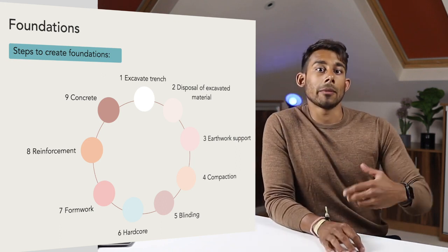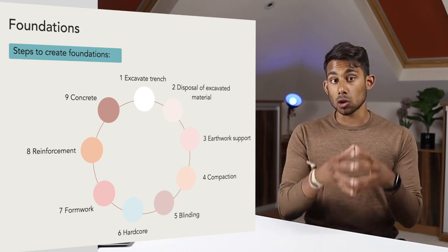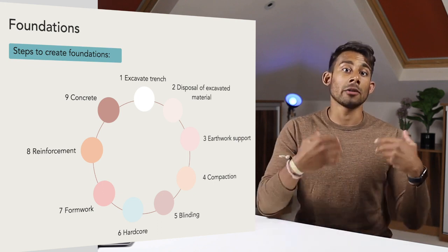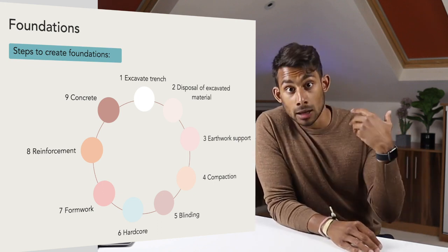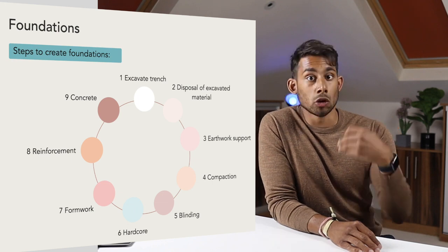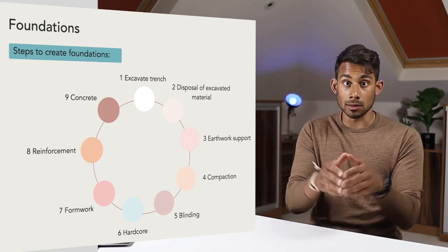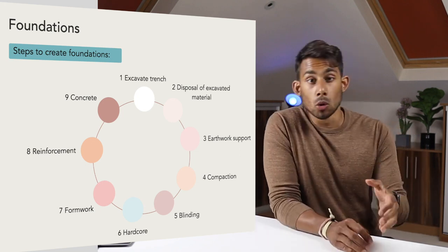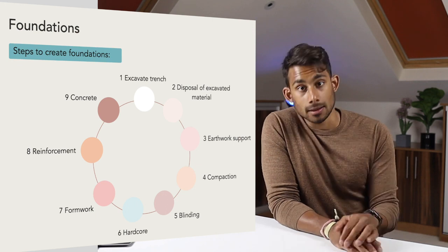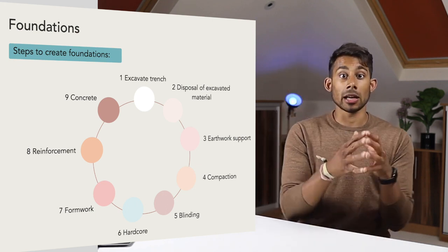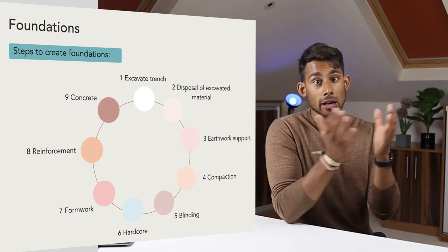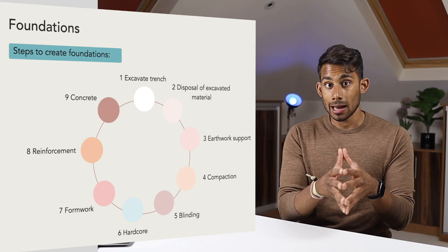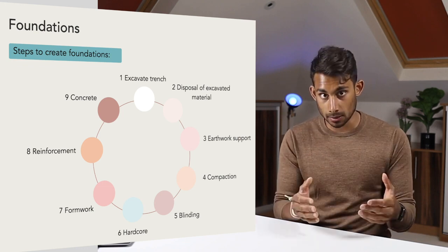For strip footings or strip foundations, this is generally to undisturbed solid ground, while for individual footings or pad foundation and floor slabs or raft foundations, you will need to allow enough depth for your sub-base, normally 100 millimeters, and damp-proof membranes, the DPM, as well as the concrete itself. This would be much quicker and easier with a small mechanical excavator, providing access allows. However, depending on the size of foundations required, the level of plant required will change. All debris, stones and plant materials must be removed before levelling and compacting the soil to create a level base.